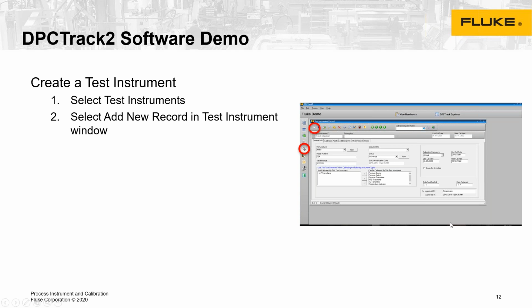You can also denote for the technicians what types of devices can and cannot be calibrated by that specific calibrator. And then off to the right side, the frequency of calibration needed. The great thing, not only does it tell you when you need to go calibrate your pressure transmitters, but it also will remind you when you need to send your pressure gauges, your multifunctions and your temperature calibrators off for calibration.